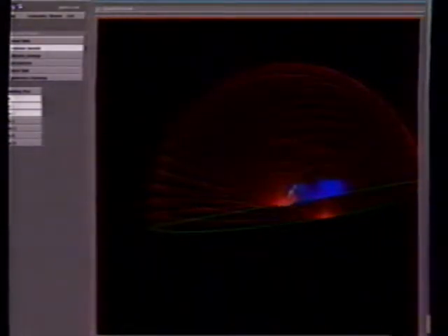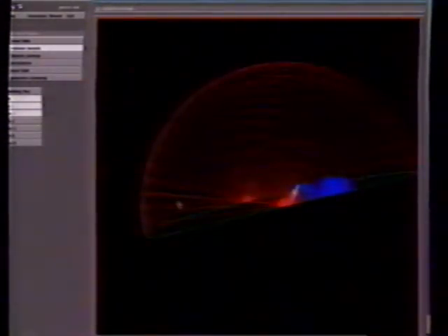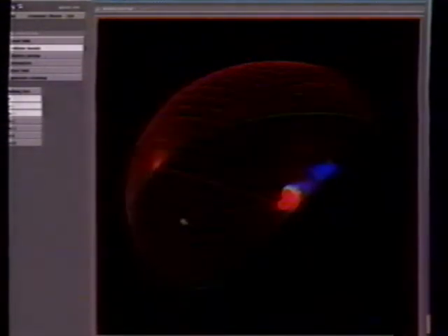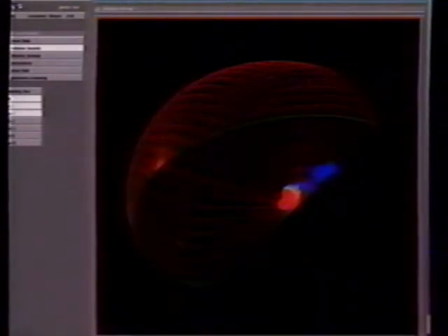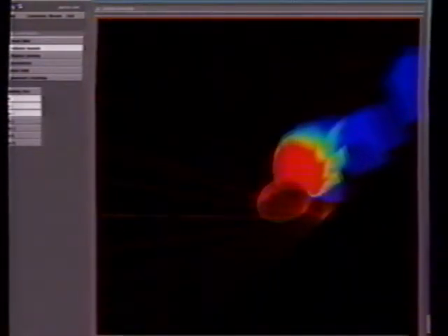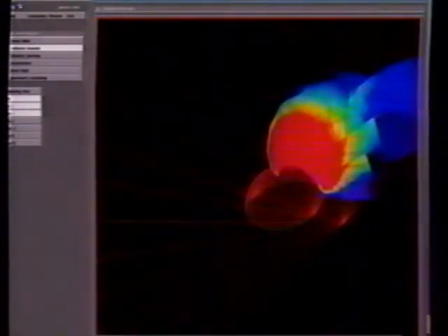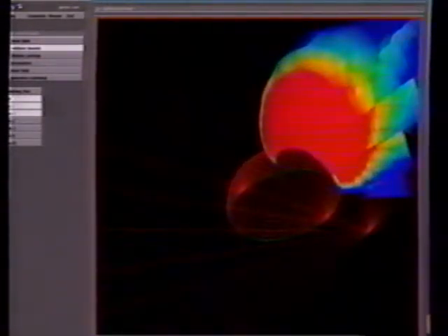They model a single droplet with a high-speed gas flow past it. This modeling process involves the use of a curvilinear grid. Shown here in red, the outer shell of the grid is a sphere, which concentrically gets smaller and smaller as it approaches the droplet. Scaling up the image, we can see the droplet itself is represented by the inner red grid.